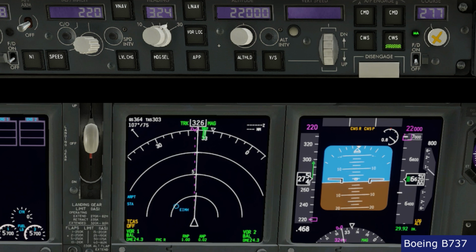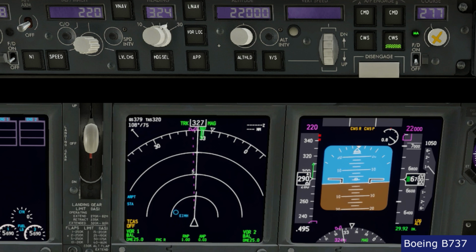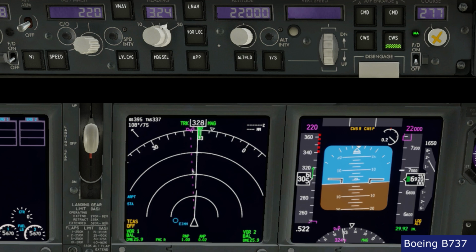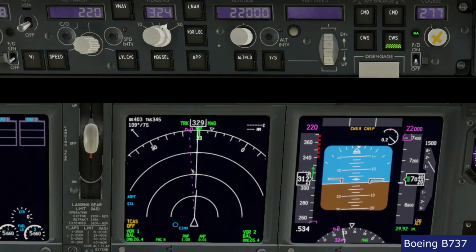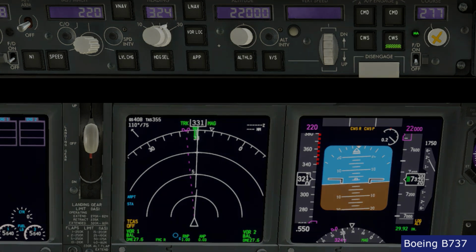Now obviously with 2 degrees and a half at this increased speed the aircraft would be climbing. Before we were in level flight, but as you very well know, if you increase the speed you require less pitch, and so maintaining 2 degrees and a half the aircraft is climbing. But as a matter of fact we maintained the pitch constant despite the variation of speed, so the autopilot is not tracking a path, an altitude, a vertical speed or climb or something like that. The only thing we're tracking is 2 degrees and a half, the pitch that I set in the beginning.